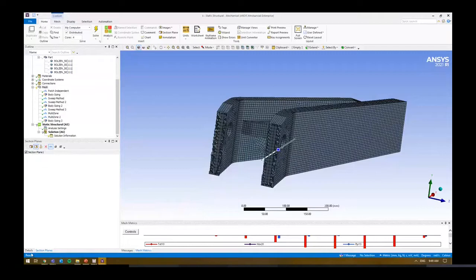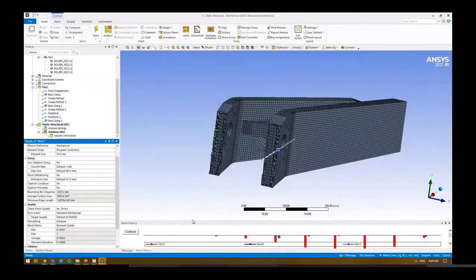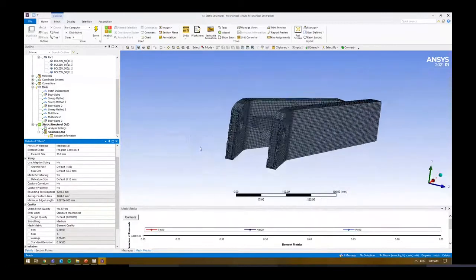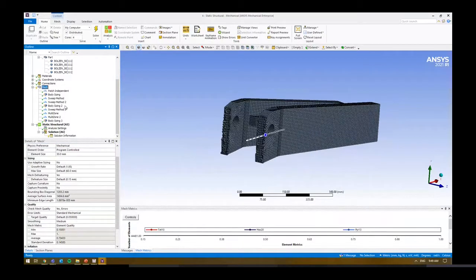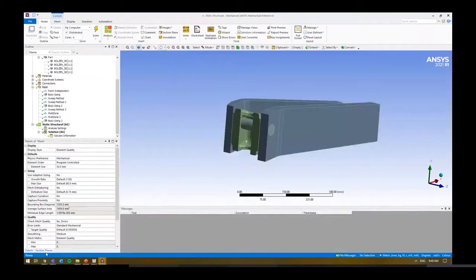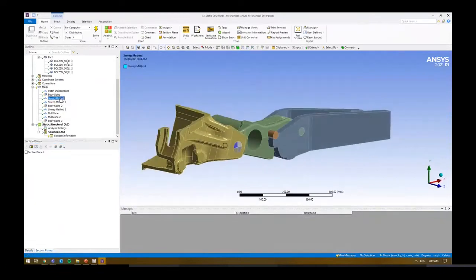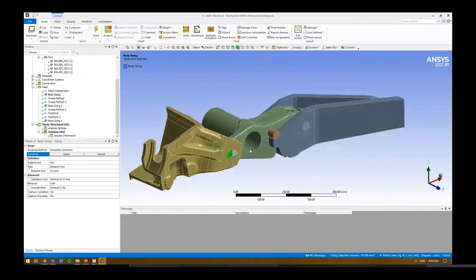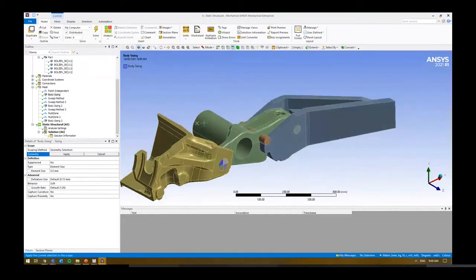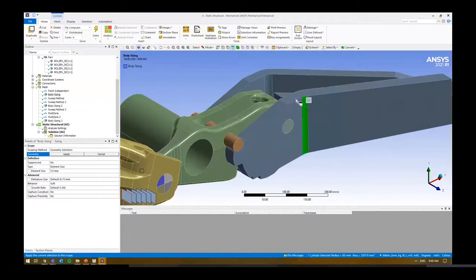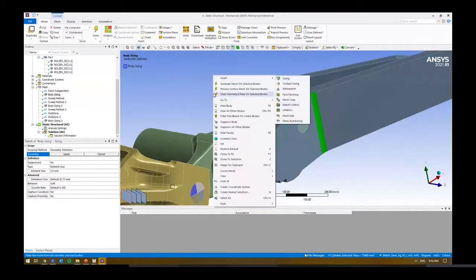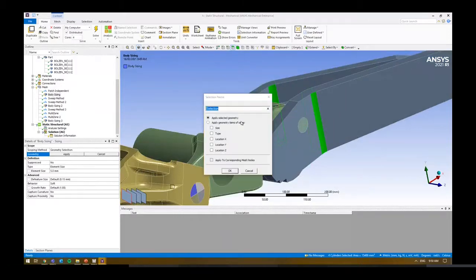Right. So if you're not sure, have a look, generate it, have a look at things like the meshing quality, look at what the good and bad quality elements are, and then start to look around that region and what's happening around some of those conditions. Right. Now, the other thing that we haven't talked about, but let's have an attempt at, is using name selections. Previously I've been using the geometry here and just selecting the geometry components. If I did, I can select, let's just say, these faces here. I can use my name selections at the bottom. I can create a name selection from it.